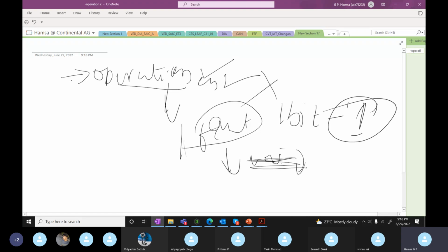So what the ECU does at that time is that the first bit will become 0, and the second bit it will make 1, because I am not sure. In the previous cycle the fault was set, but now it is not set. So I am not writing the DTC. I am still writing this as a pending DTC.